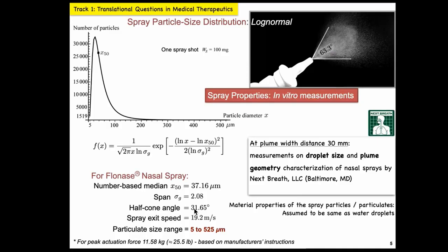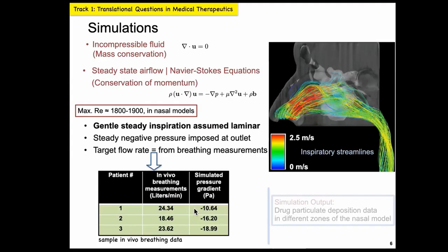So your second question, can you repeat that again? What's the computational cost for your simulations? That depends on the kind of numerical scheme that we are using. If it's laminar, we don't use any kind of supercomputer, by the way. We are using ANSYS, and we are using parallel processing on just workstations that we have in the lab. So for the laminar simulations, it takes around 4 or 5 hours. For turbulent simulations, we typically use LES. That can take around 3 to 4 days. And if the problem is simple enough, and if we are confident that we can just use RANS, then that would take around 12, 13 hours.